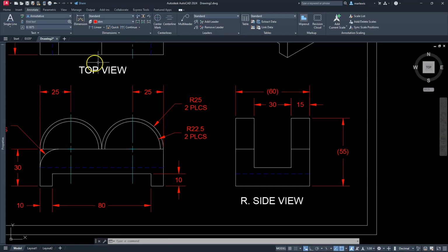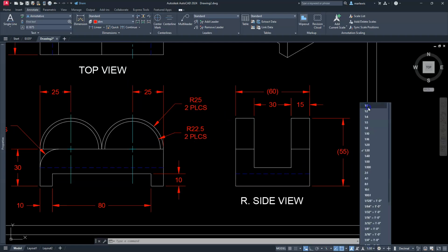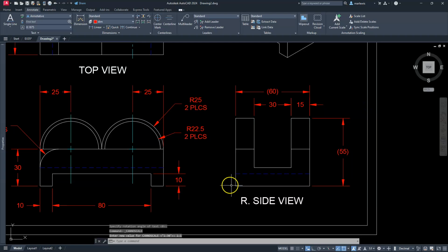If I'm using the standard method, remember, you have to do the multiplication. If you're using the annotative scale, then you don't. You just type in whatever size you want the paper to be. That's the most important difference between using paper height or annotation versus the standard. So I'll set this back to 1 here, just so I'm not confusing myself, and do a regen.